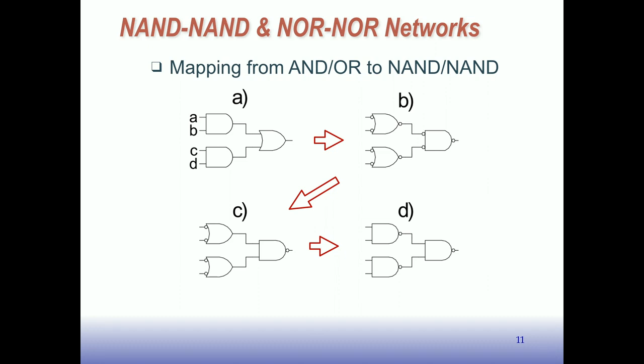Okay. So the thing to remember is AND-OR circuits can be implemented as NAND-NAND, which is kind of nice, right? Because if all you have is a NAND gate, that's really all you need. You can do all your sum of products things with just NAND-NAND. Right. And I'll leave the other ones for homework. Well, okay, I could tell you this.